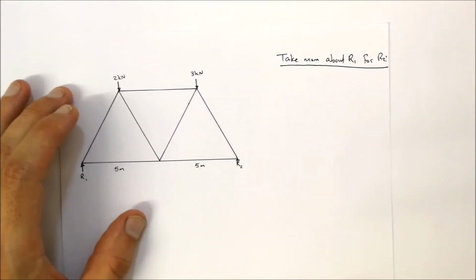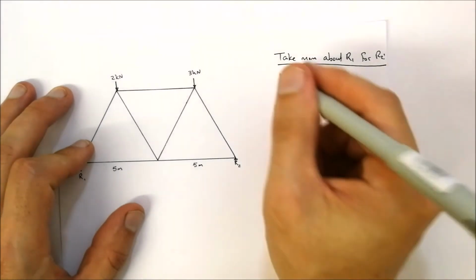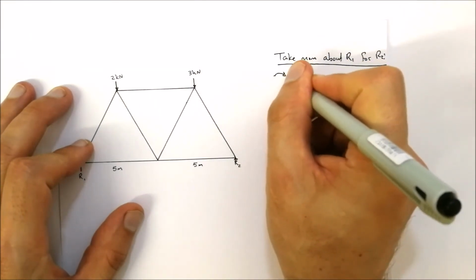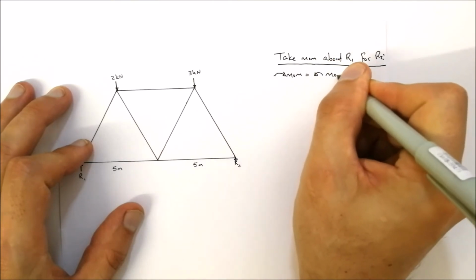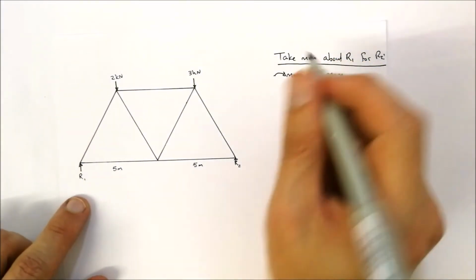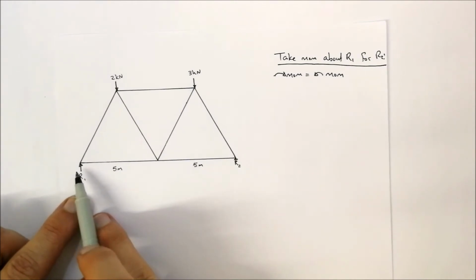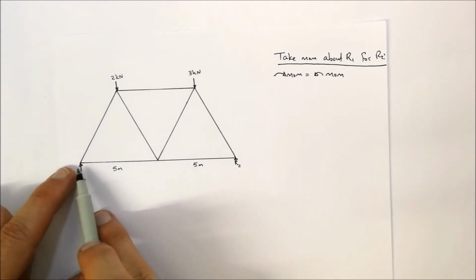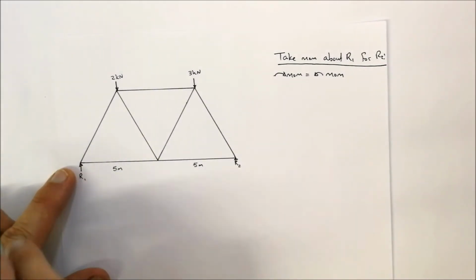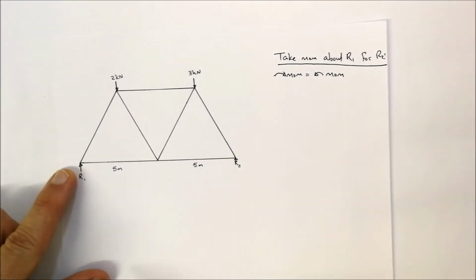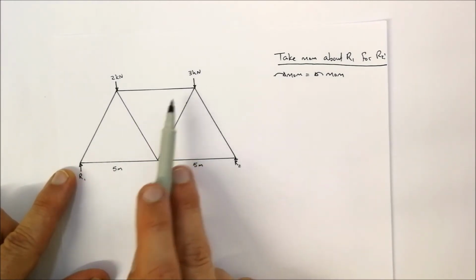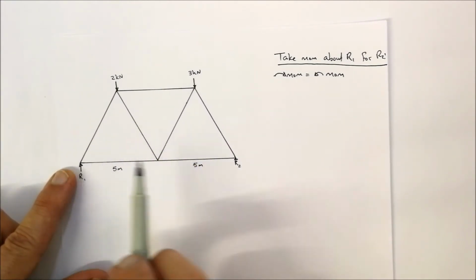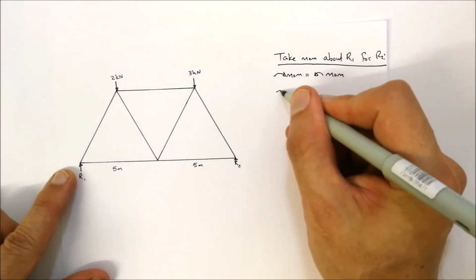Okay, so remember, anti-clockwise moments is equal to clockwise moments. So we're going to be looking at R1. We're placing our pen on R1, and we're going to be looking at all the clockwise moments. That's going around it in a clockwise direction, and that would be this 2 kilonewtons and 3 kilonewtons that would be considered as part of it. So we've got that 2 kilonewtons over there.